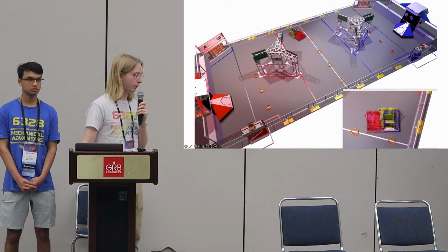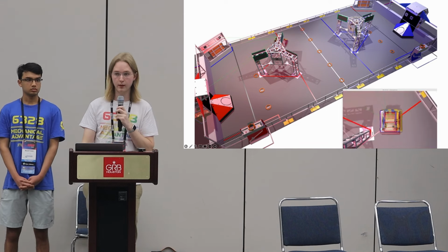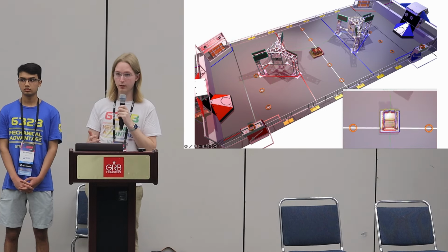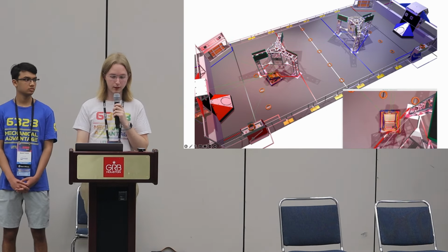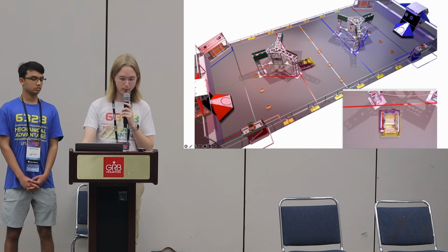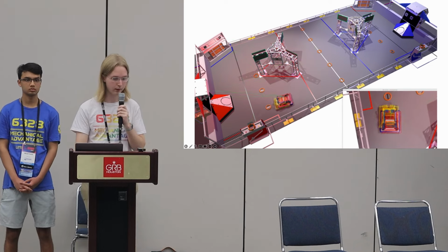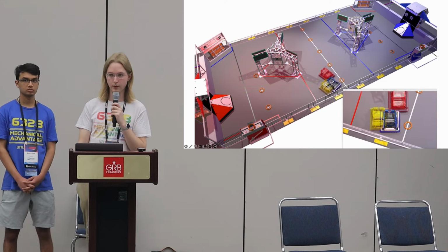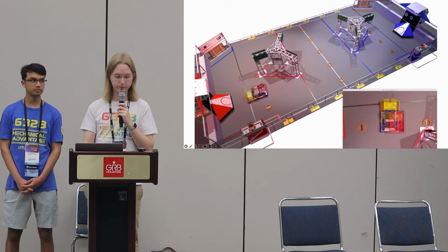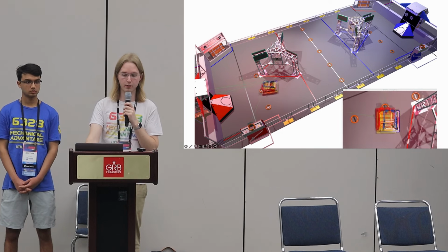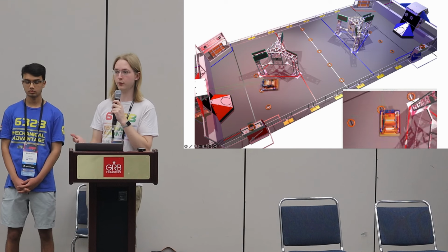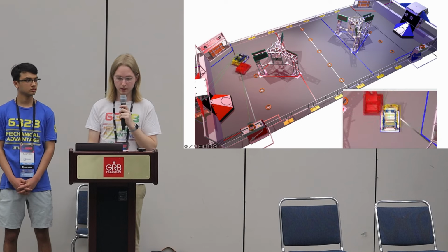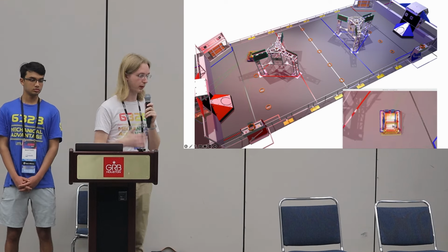Now in 2023 and 2024 we used 4 cameras on each robot and a variety of filtering techniques. But we were wondering how much those helped us, so we used log replay to check. Here you can see that the solid robot represents our standard pose estimation with 4 cameras and normal filters. The yellow ghost represents what our pose estimation would have looked like if we had 1 camera, but still with our normal filters. And then the red ghost is kind of fun. That shows, with our 4 cameras, what if we were using very simple filters rather than our fully tuned version. And you can see that the solid robot is tracking much more smoothly and realistically than the other options.